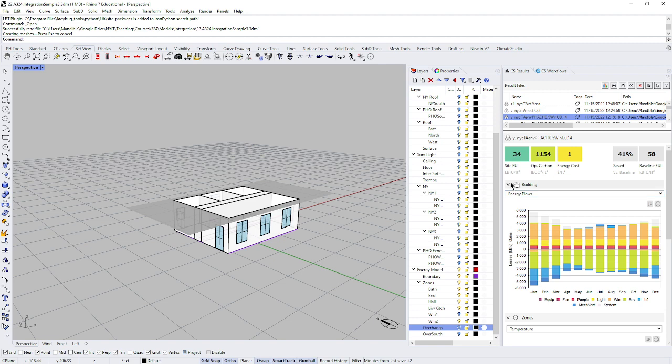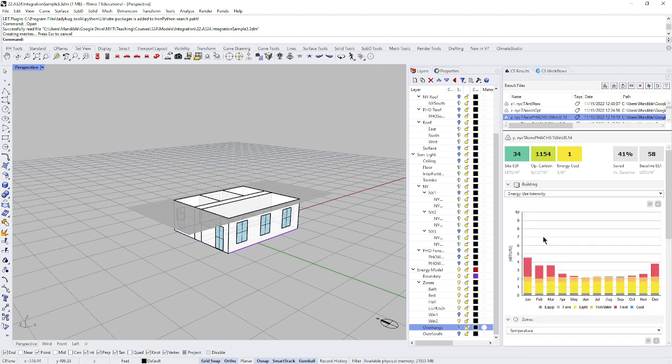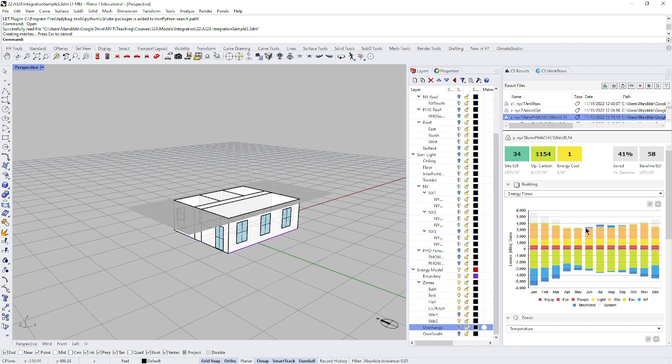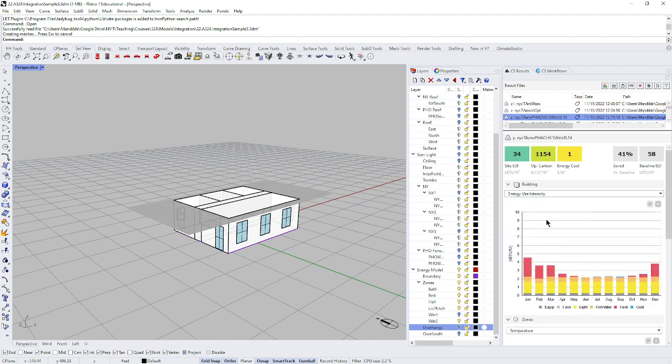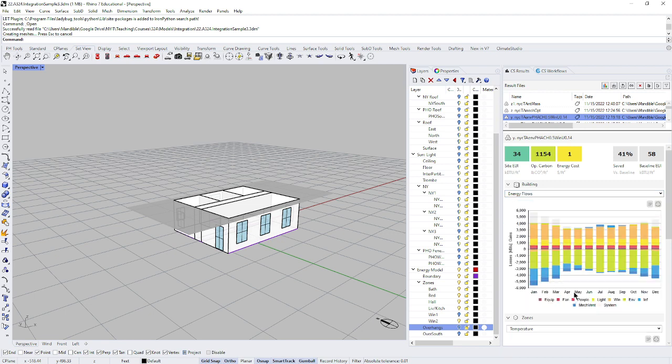We just saw that we had heating load, so those windows are actually decreasing that for us. So that's great. But in the summer, we see we're still getting some heat gain, and we wouldn't want that because we're cooling at this time. So we could try to shade the windows or do something to reduce this, though we don't really need to since we don't have a cooling load anyway. So that's the way we were using this, and it made a lot of sense. And then we could talk about the envelope, etc. It made a lot of sense in terms of what we were doing.